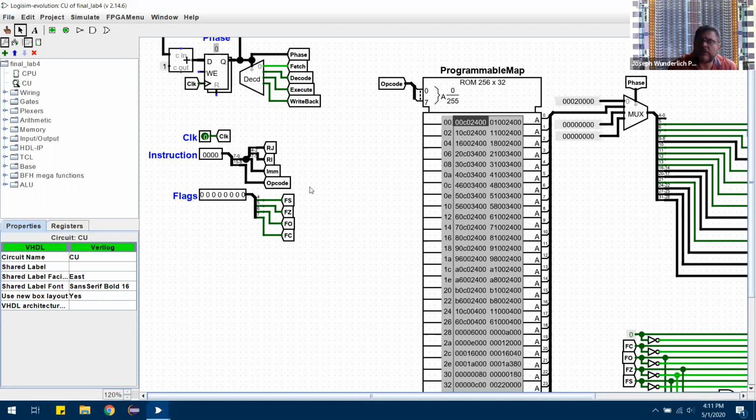When you say you're only using the fetch and decode, is that because everything just kind of flows as soon as you decode? All the pathways open, everything flows. So you're not having a set stage where you bring things into queues, buffer them right outside the ALU, and then have a whole finite state machine phase for pushing. Yeah, basically. So you just kind of open all the pathways. In physical practice, it might be better to have that split up. You actually do need to if you were looking at timing traces, because you've got to let the thing settle. If you just let everything flow, you can have weird race conditions. You don't want everything coming into the ALU at different times, because you could be adding something that was previously there.